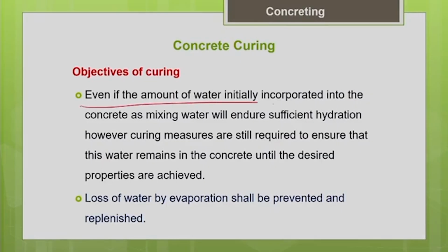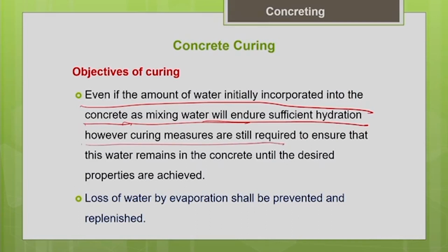Even if the amount of water initially incorporated into the concrete as mixing water will ensure sufficient hydration, curing measures are still required to ensure that this water remains in the concrete until the desired properties are achieved. Even though the water you have added for concrete making is sufficient, you still have to do curing, so that you can prevent the loss of this water to the outside environment.